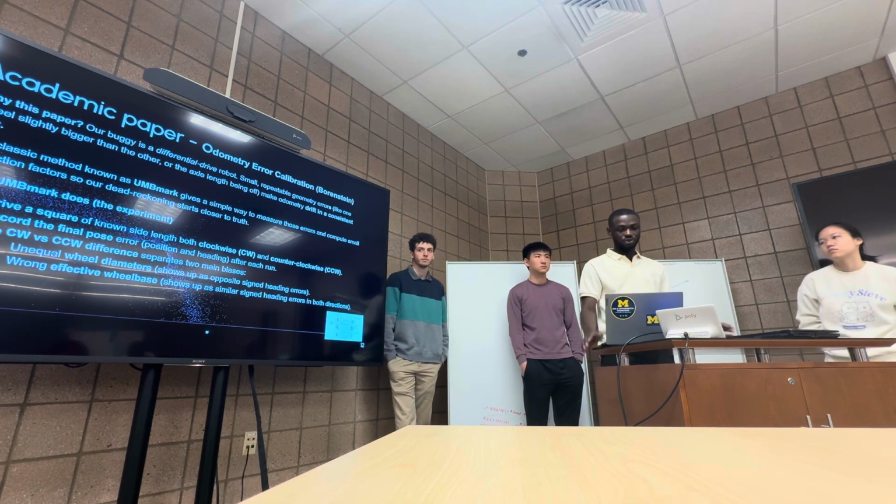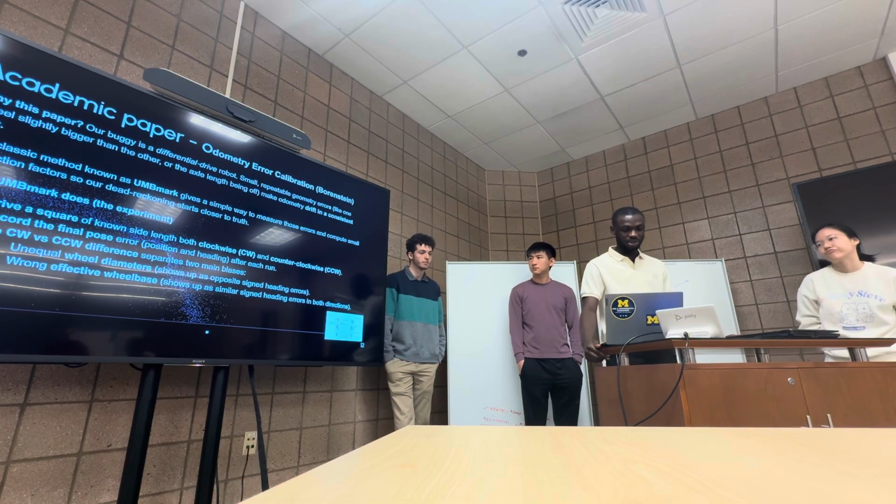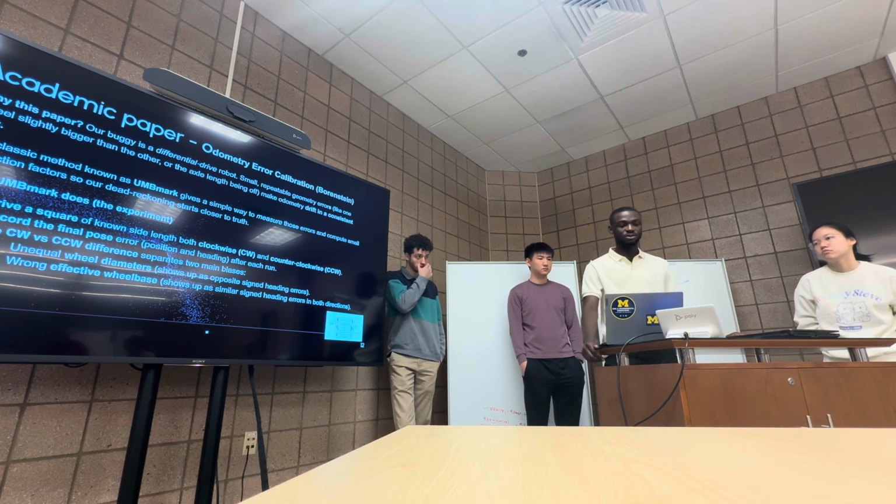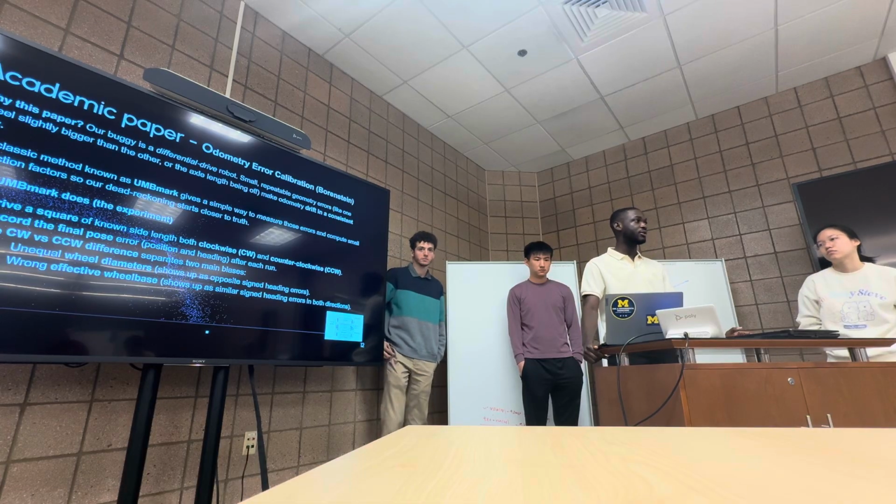What the UMBmark does is that we first drive a square of known side length both clockwise and anti-clockwise, then record the final position errors.